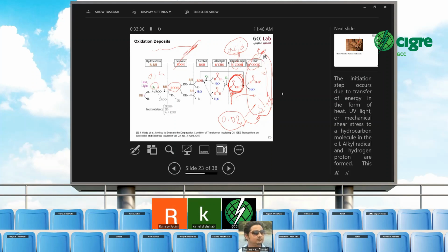In this case, you have overheating in the cable. You must find a solution for this one. We did some study, and actually those cable boxes are kept under close monitoring. But we got some counter response from the manufacturer that it is stray gassing and not partial discharge.